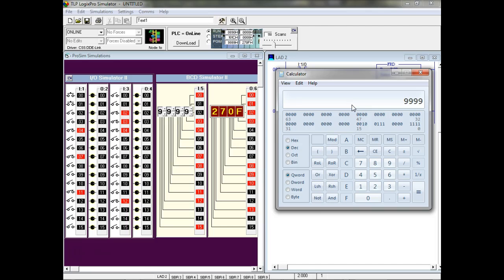And it gives me the ability to bring in BCD, our decimal numbering system, and do what? Convert it over to binary for my counters and all that other kind of stuff. So I could display the output of a counter, even though the counter's displaying in decimal up here, it's actually in binary.